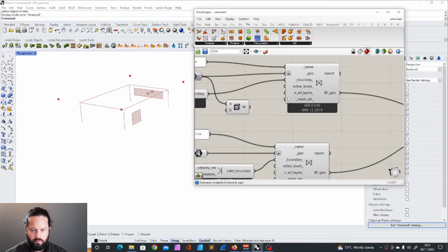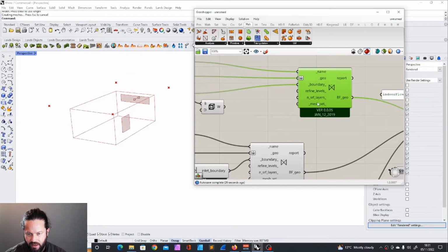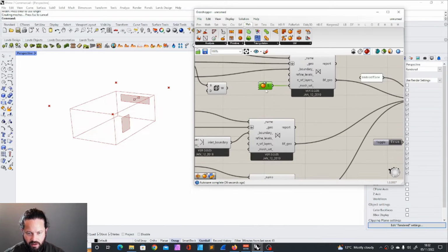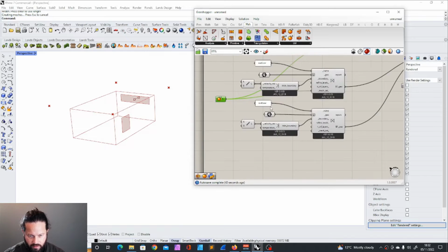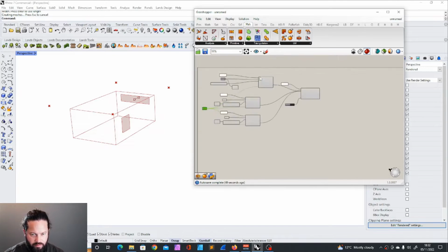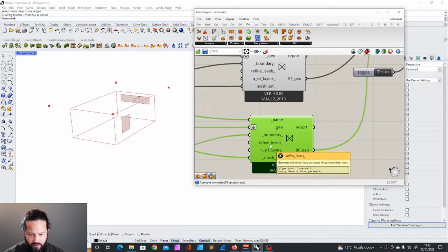That's nicer. Some things are not mandatory, but as you remember from refinement levels and mesh settings, and normally these are set by default, but we can always add here, for example, the high quality. I will do that. We can use it for all three geometries. They're not very complicated at the moment, but they could be, and then this makes definitely a difference. And the same for the refinement level.